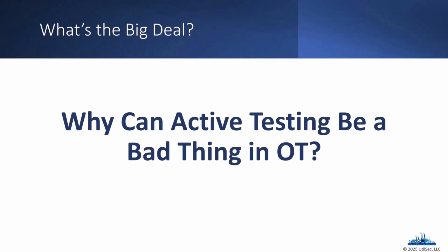And as we've mentioned more than a few times, and I'm sure you'll hear me mention it again, we can never suggest that anybody does active testing inside a production environment. I've shared a couple of stories. When I was at DEF CON earlier this year, I had two different people working in two completely different power plants mention that there were outages caused by people running tools like Nmap or Nessus. And then there was a podcast I was listening to by two gentlemen that were doing active pen testing in a power plant using Nmap, and brought the plant down.